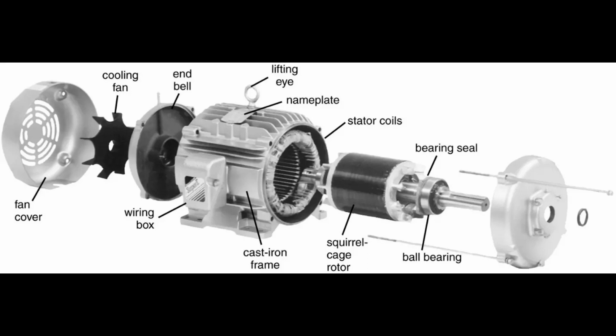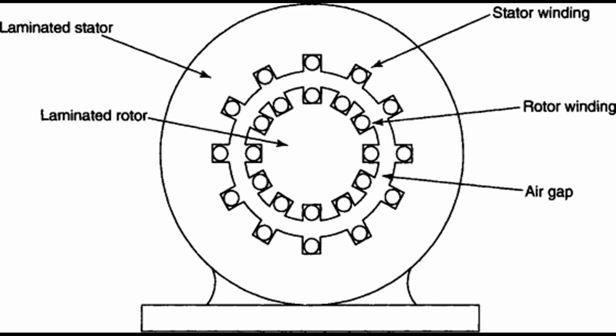Here's how the alternator charges the battery. The alternator generates electrical power as the engine's mechanical energy is converted into a rotating magnetic field by the rotor. This rotating magnetic field induces alternating current, AC, in the stator coils through electromagnetic induction.